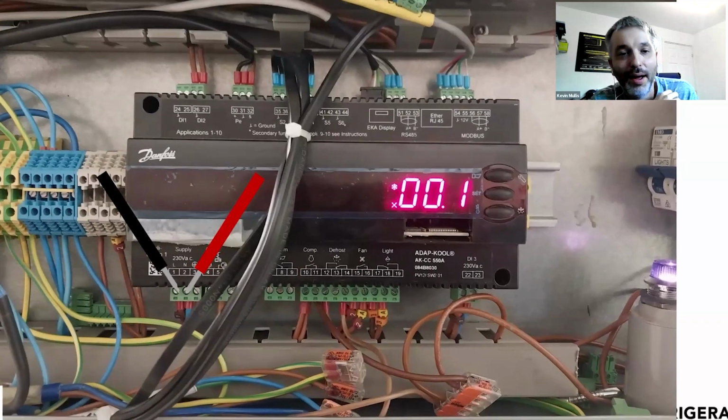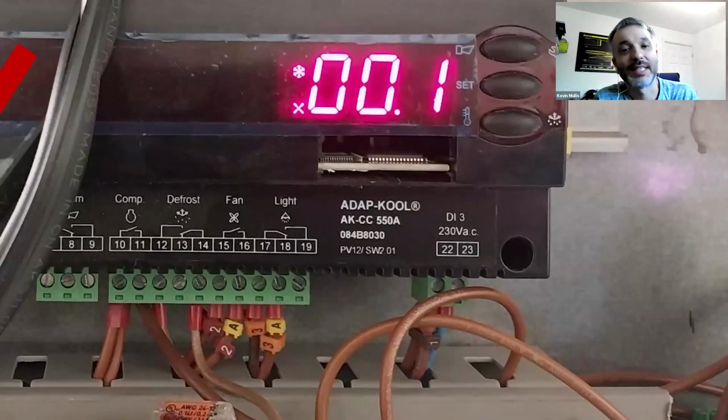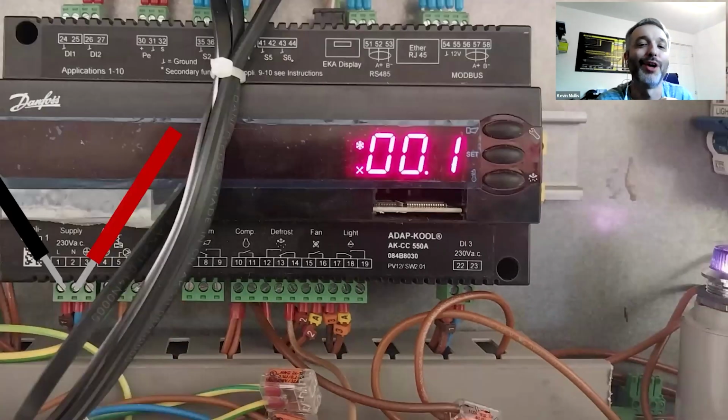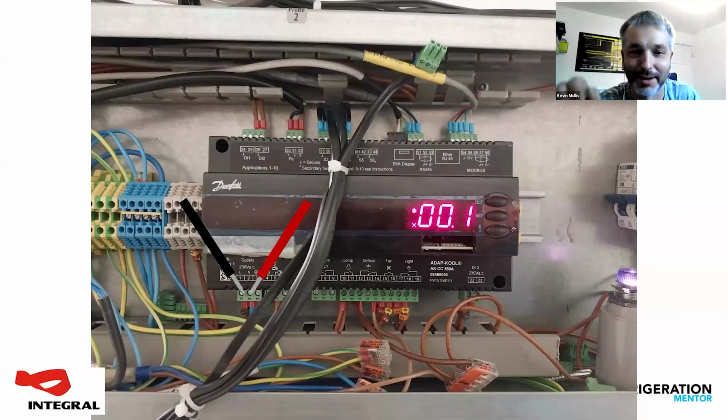And yeah, just bear in mind, and for testing as well, so DI3, and that will be your line voltage. It doesn't matter which way around the wires are. All it's looking for is the voltage difference across it. But bear in mind, yeah, that is not going to be a happy controller if you plug that into DI1 or DI2. I think that's why they put it on the opposite side, to make it really difficult to get the wire around.